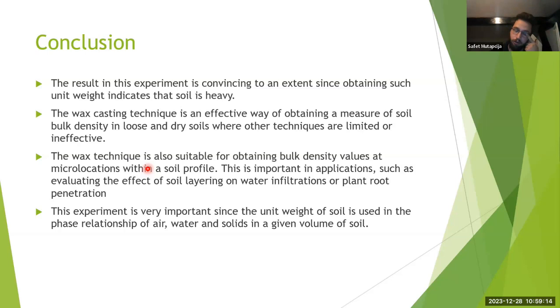The usual procedure is to do excavation pits to like 2 meters depth, depending on where in the world you are, what kind of soil you're expecting and what you're going to build. Or what you would normally do is drill a borehole with continuous sampling. The depth of your borehole is going to depend on the type of construction, the type of expected foundations, and on your budget, of course.